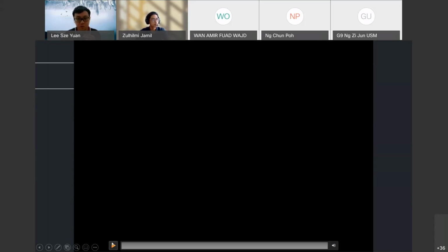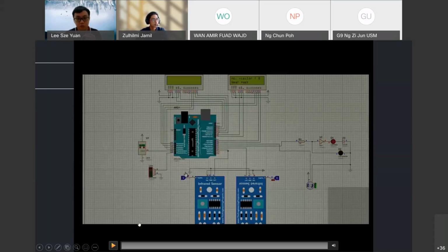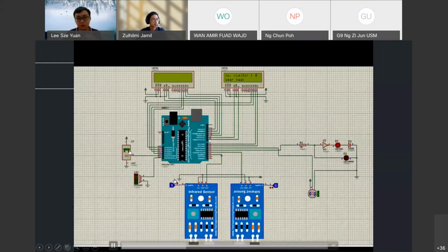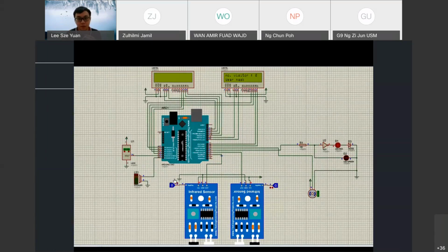So this is the first condition I say. Press the infrared sensor when it is on, and the temperature. And since here it is 36 degrees Celsius, the green LED turns on, the motor turns on, plus 1. So this is the second condition, higher than or lower than the range. Now here we have 30 degrees Celsius, 38 degrees Celsius.